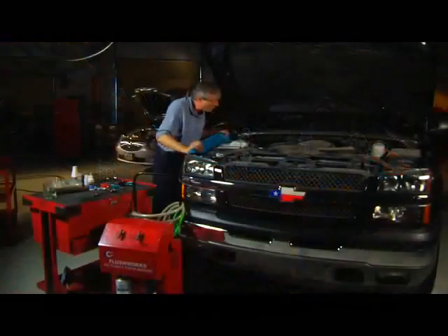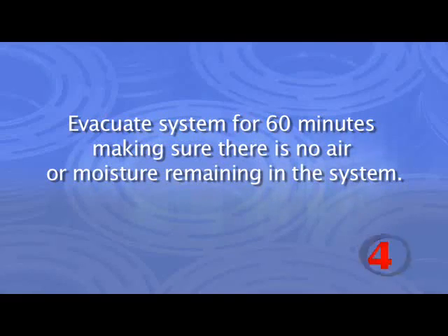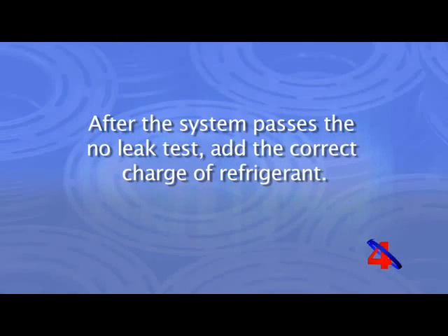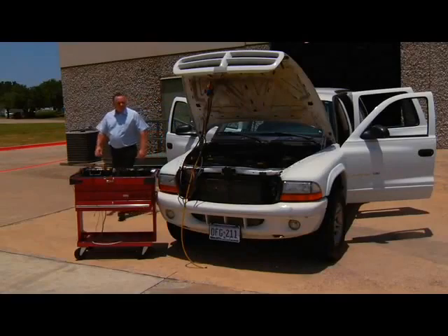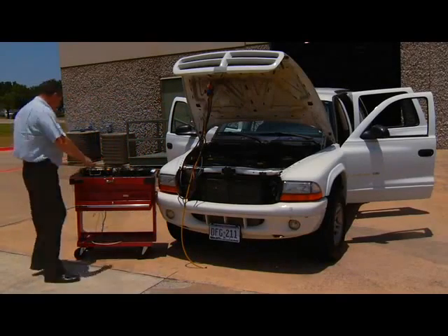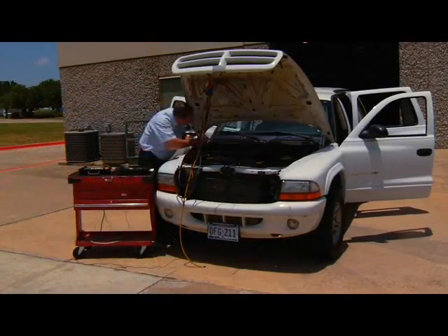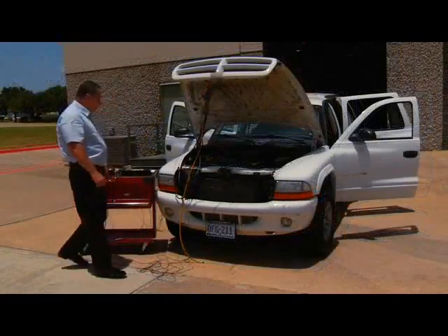With the system back together, evacuate it for 60 minutes, making sure that there is no air or moisture remaining in the system. Once the system passes the no leak test by maintaining a vacuum for 5 minutes, add the correct charge of refrigerant. Before returning the vehicle to the owner, perform the after repairs temperature stress test to make sure every component is performing to specifications.